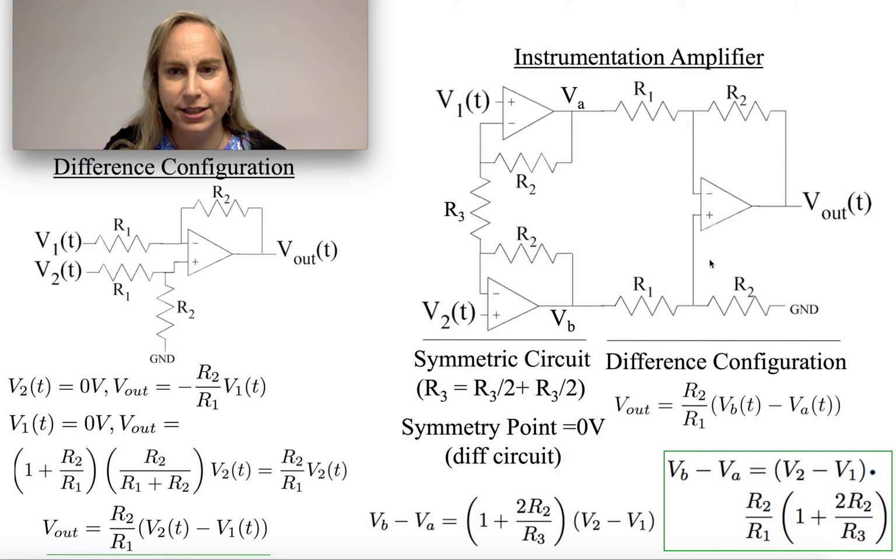Then you start to get this classical instrumentation amplifier. If you look at it, you think, why would I want to do this versus this one? Again, notice that in this case, V1 and V2 are both going into terminals of the op-amp, which means that it is completely isolated. So it also buffers whatever I'm measuring from whatever the output is. Plus, it gives me an opportunity with more resistors to have more gain stages. There are a few other things that can be important in getting an even better differencing structure, but basically this is a pretty typical and classical circuit that you'll see almost everywhere.